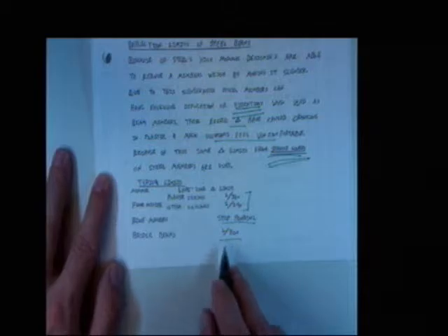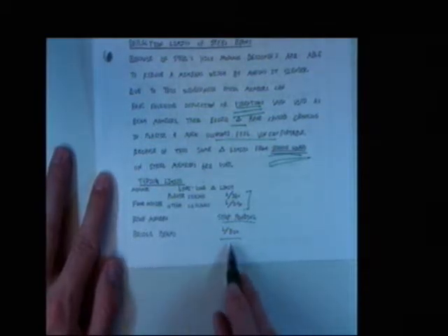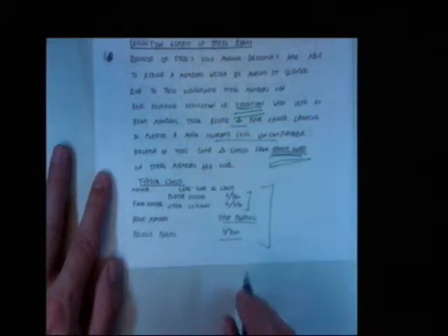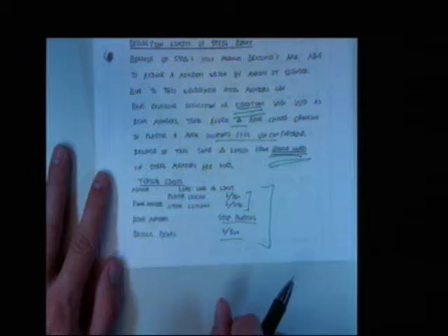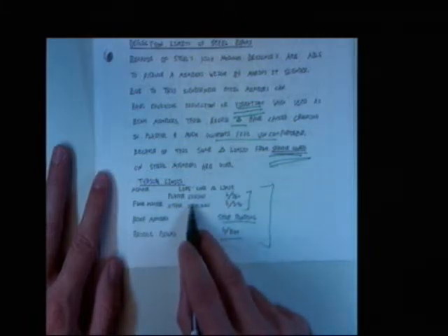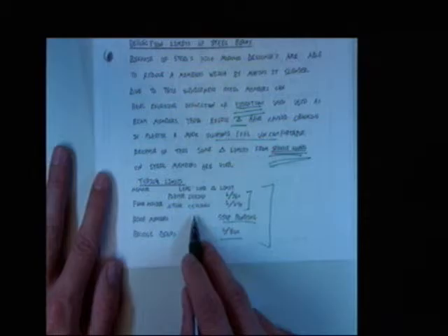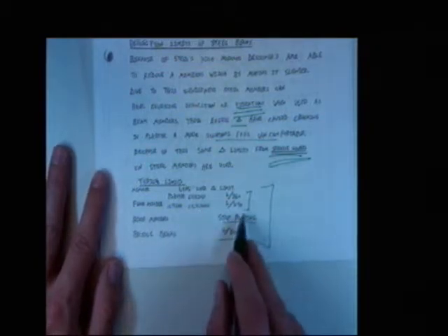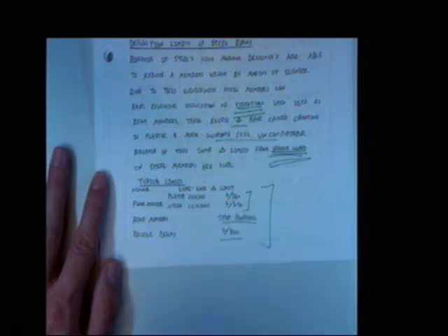They'll also make bridge beams have much more stringent live load deflection limits. Again, please realize all of these are made up. All of these are not real. Only in the case of causing cracking in plaster ceilings or in your walls are these real deflection limits. They're often just substitutes for doing a much more complicated analysis.